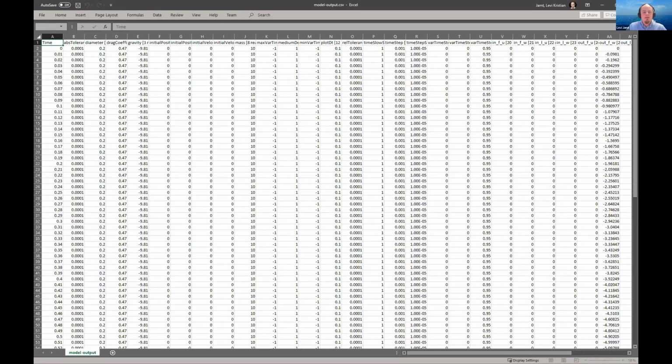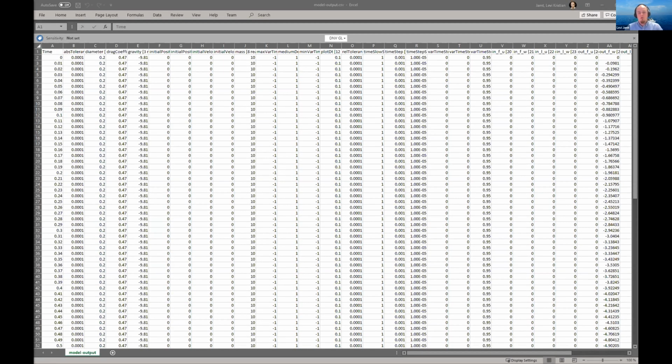We did not provide any initial values when running this mass model in single mode, meaning that the mass now started with default position at x0, y0. And with run single, we simulated just the mass model, so it was not connected to the spring or damper. And as gravity is part of the mass model, it should now be free falling.